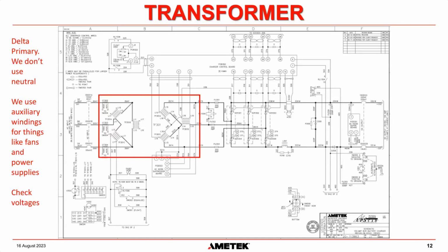If you're getting a new charger from us, all we need is 3 wires and ground, not 4 wires and ground. It's only 3 wires and ground. We just need phase to phase and a ground connection. We do not even have a terminal for you to run a neutral to our chargers. And our chargers are not phase rotation sensitive either. They do not care about the phase rotation of the input into the system.